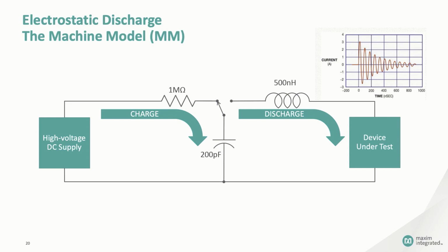While you'll still see the machine model mentioned, you ought to know that JEDEC has discontinued the use of the machine model, and the ESD Association, an industry standards group, has argued in favor of its abandonment by the industry.